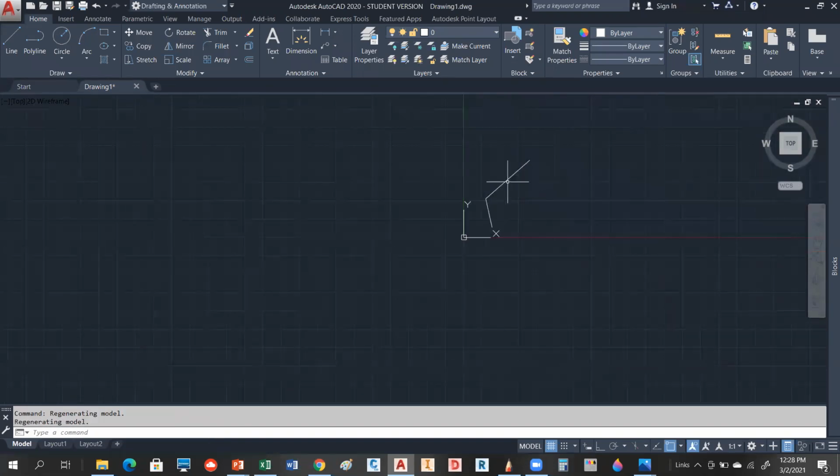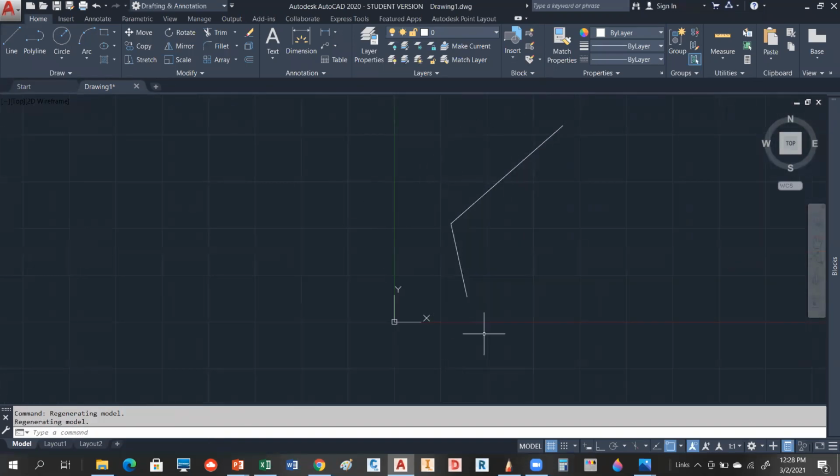Okay. So what you're going to do is come around, and your lines probably won't close. That's not a big deal, but I would like you to label them. So that would be A, B, C, D. You can put your distances on those lines and/or bearings. It would be nice to show both. Okay, so that's what I'm looking for.